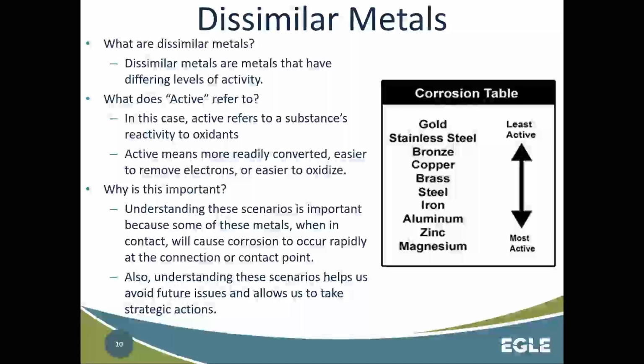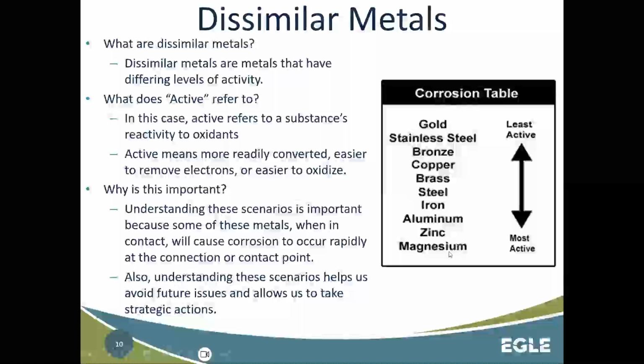So you're putting in those sacrificial anode rods to be that sacrifice, more willing to give up that electron to then protect that thing that's on a lower activity level, steel or iron in this case, okay? So we put these things in here, knowing full well that they're going to corrode, they're going to degrade over time to protect these things from this concept of dissimilar metals and corrosion in general, okay?